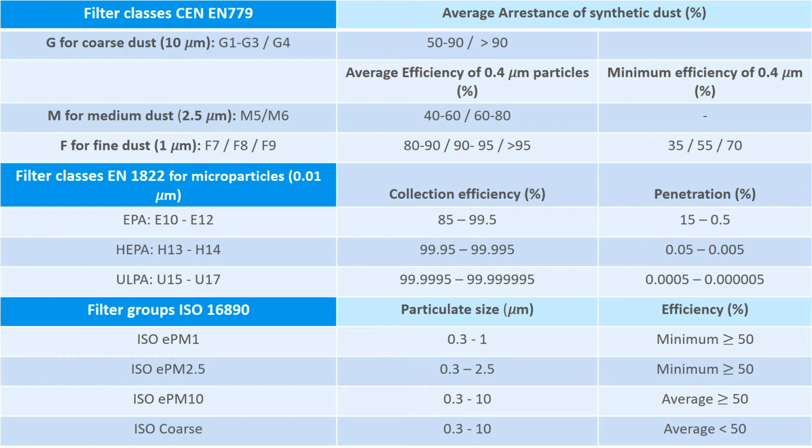In air handling units of clean rooms and operation theaters, usually HEPA or ULPA classified filters with a higher number are used, while filters that are used in the air inlet to protect the system from larger particles usually have a lower number, M5 or M6 for example.